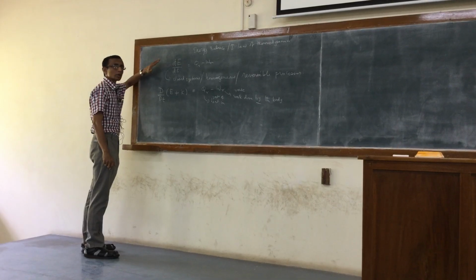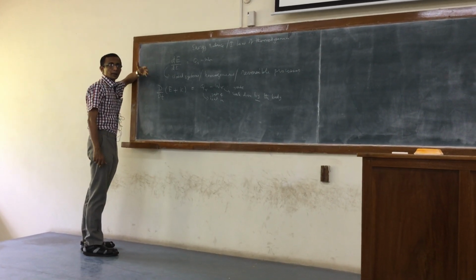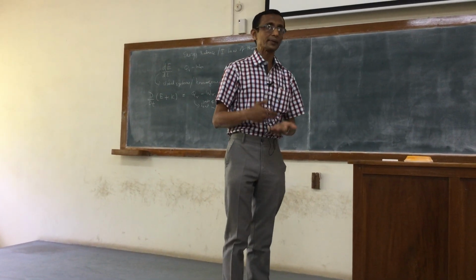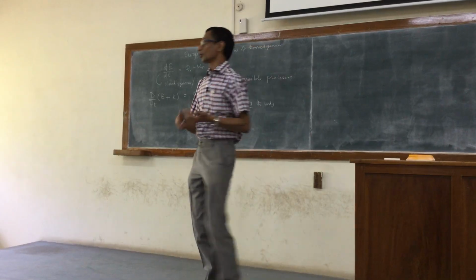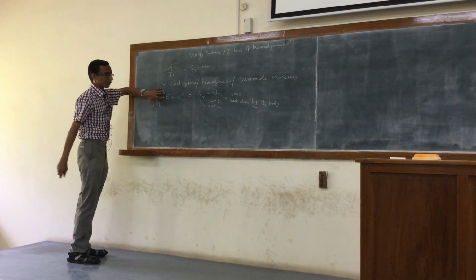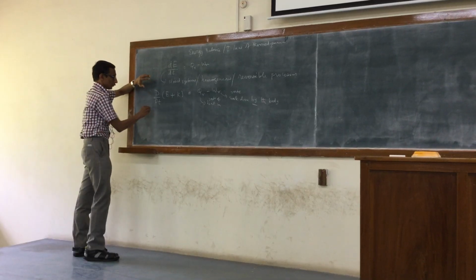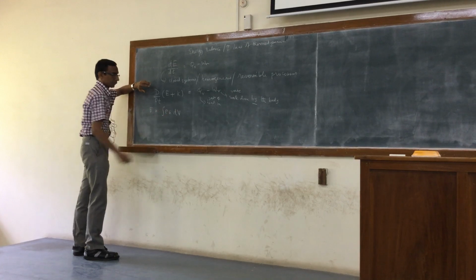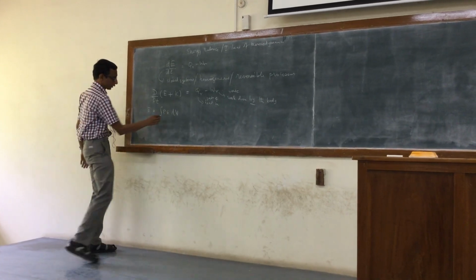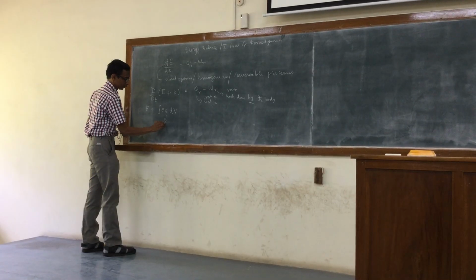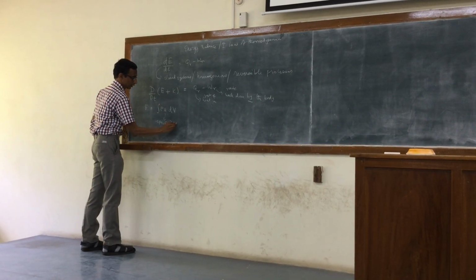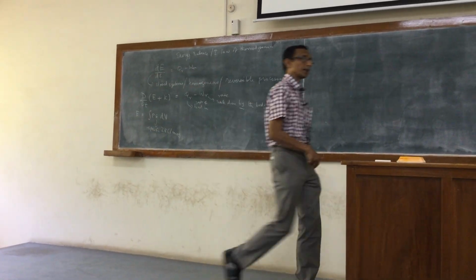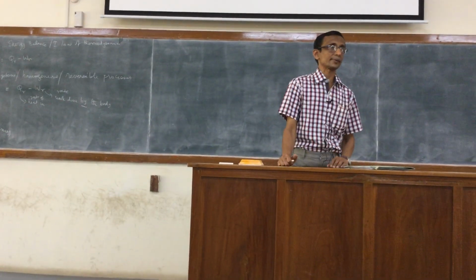Internal energy is the total internal energy of the body, but just as we have the total mass of the body, the mass density could vary from point to point. So to take such effects of the continuum into account, we will represent E as the integral of rho times epsilon dV, where epsilon is clearly the specific internal energy, here per unit mass. So internal energy per unit mass defined at every point in the system.